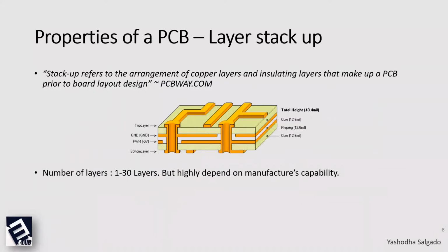Okay, then we jump into the layer stack up. Layer stack up is the way of arranging the layers. When we talk about a PCB, it's made of several layers, and not just electrical layers. There are also insulation layers as well.